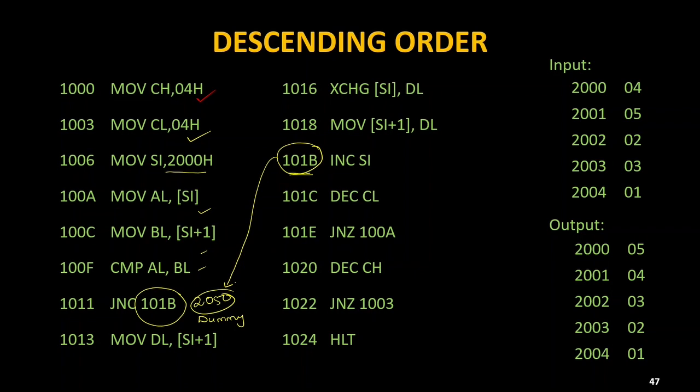In order to do that, while you are seeing your previous program, we typed with the assembler command A, and after that you give the starting address 1000, and then you start typing it. After completing all, note down this address and keep it ready. If you have forgotten that line also, you can go to that memory starting address and check one by one.